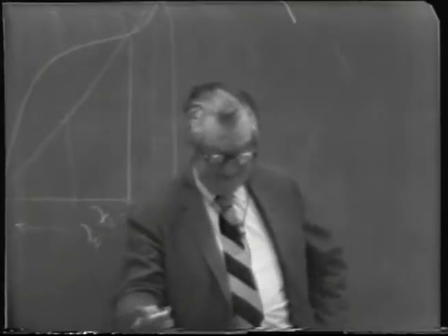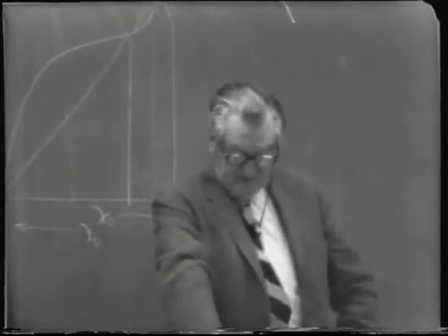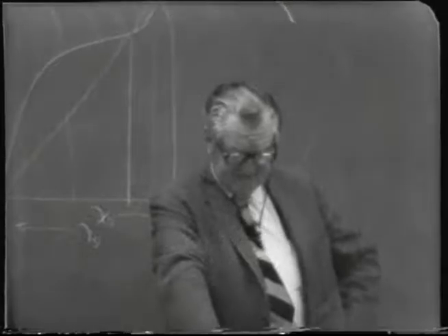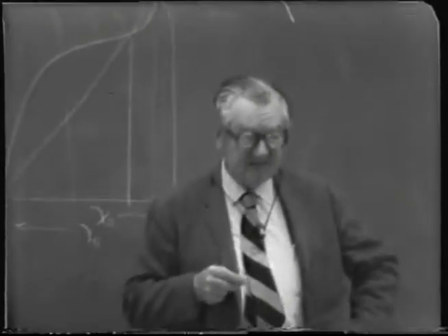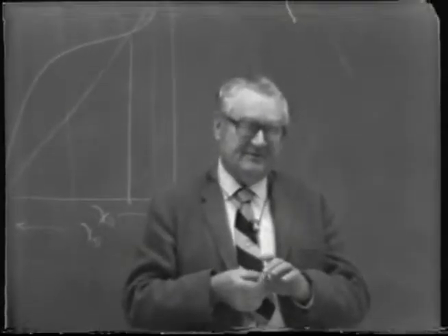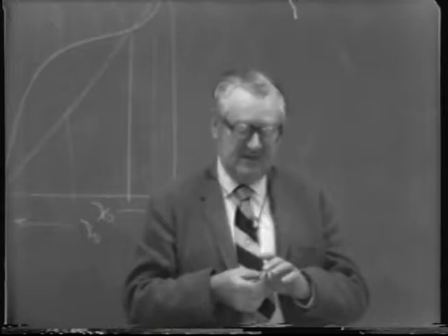So as a kind of empirical rule, they allow vapor velocities of something around 40 to 70 or 75 feet per second in the vapor lines.